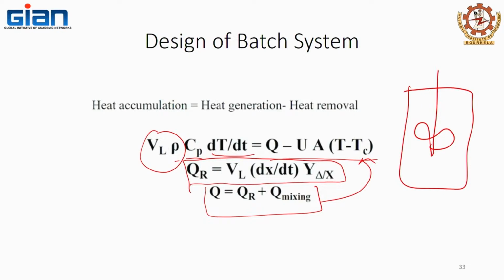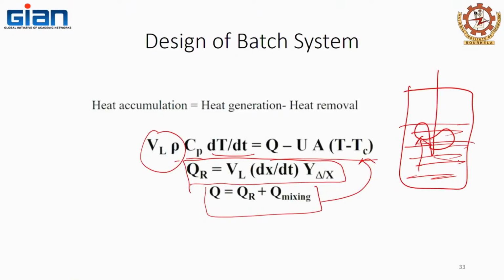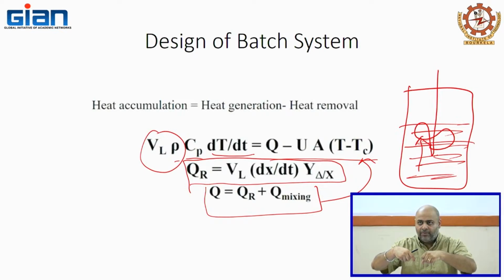See, you are forgetting two things. So, yes, there is heat which is being generated by the cell, right? Yes. There is heat which is generated by the mixing. Now, from where are you actually taking away this heat? From the surface, right? Yes. You are not taking the heat from inside the broth or the medium. You are taking the heat away from the surface.